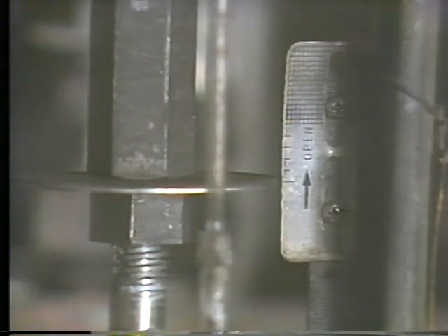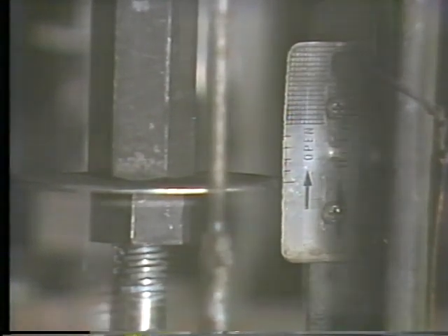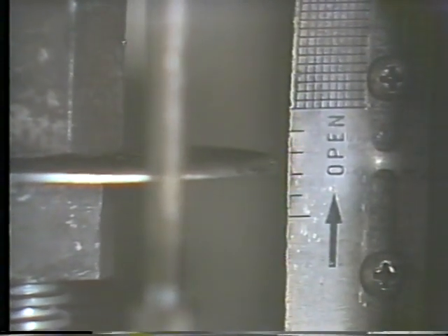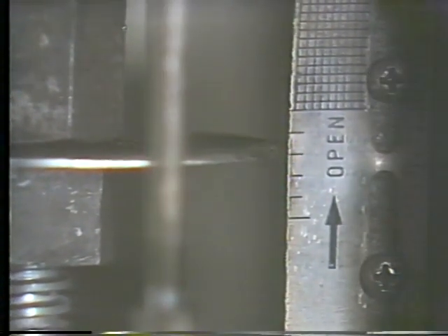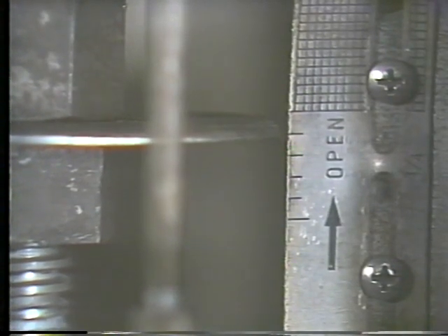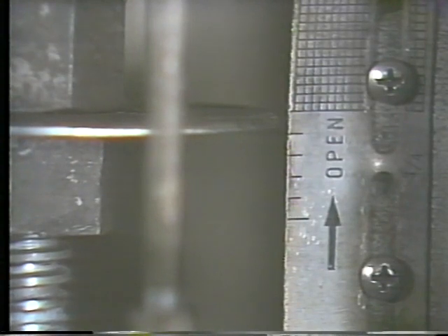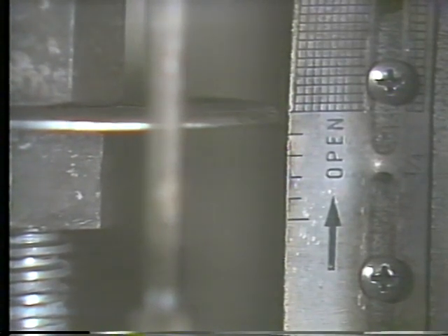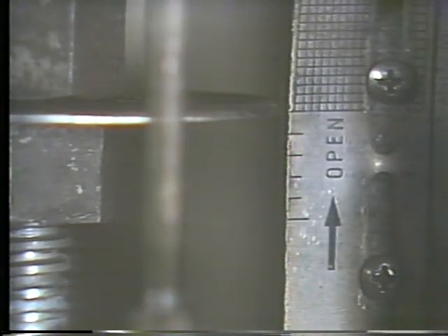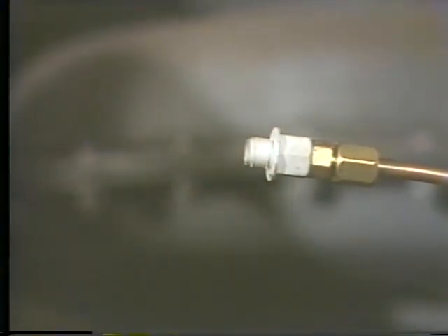To make sure that the actuator and valve were stroked properly, reapply the air supply to the actuator so that the valve opens all the way up. The indicator plate on the valve stem should be raised up so that it indicates the highest or open position on the indicator scale. Once the actuator has been run through a complete cycle and the travel is correct, then the manual loader can be disconnected from the actuator and the air supply line from the positioner reconnected.